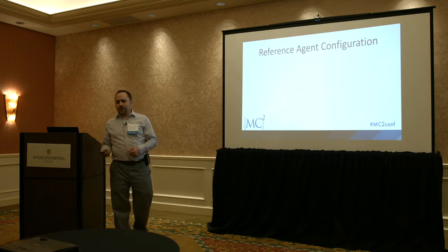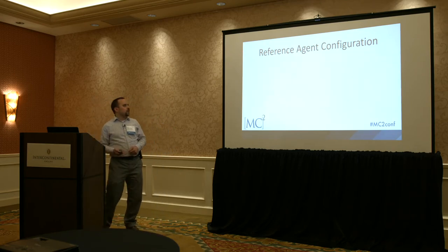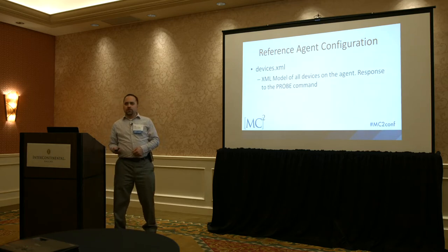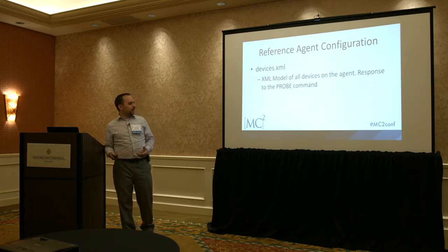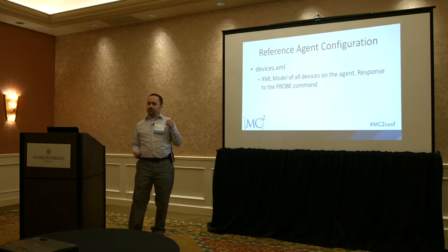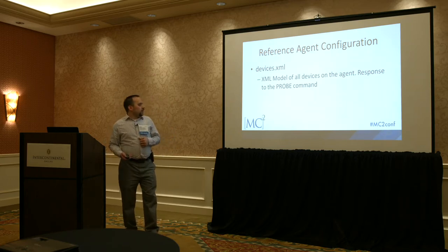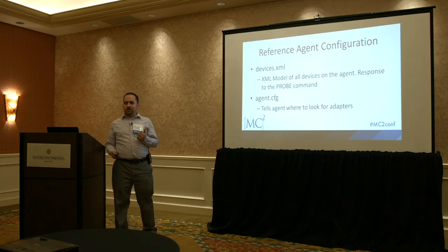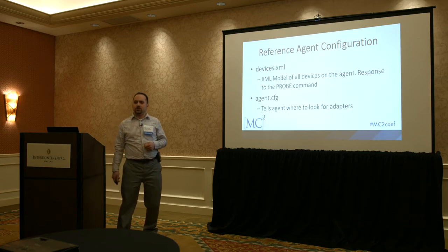With the MTConnect reference agent that's on the MTConnect GitHub site, devices.xml is the file that lays out that device model. When you do a probe command, you're getting the devices.xml file directly. And the agent.config file, its purpose is to point to all the different adapters that you might be connected to with the agent.